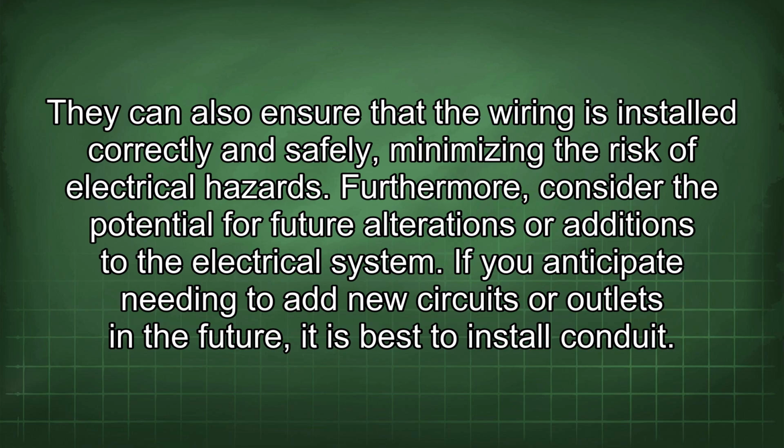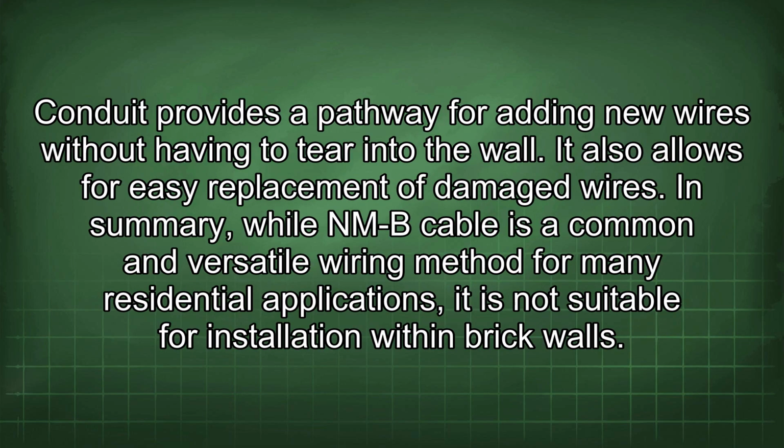Furthermore, consider the potential for future alterations or additions to the electrical system. If you anticipate needing to add new circuits or outlets in the future, it is best to install conduit. Conduit provides a pathway for adding new wires without having to tear into the wall. It also allows for easy replacement of damaged wires.